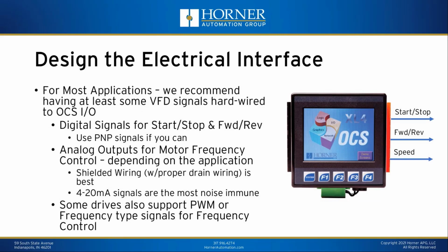Okay, let's start with the electrical interface. Okay, so for most applications, we do recommend that you have at least some signals hardwired between OCS I/O and the variable frequency drive. Now, that's not an absolute necessity. You could completely control a drive over a communications network. You could certainly do that.